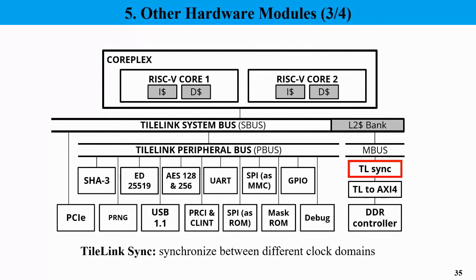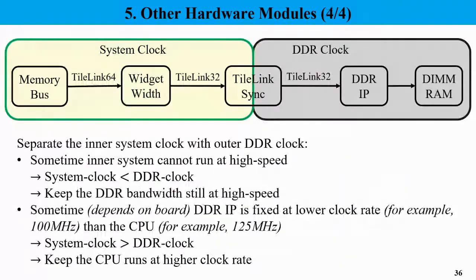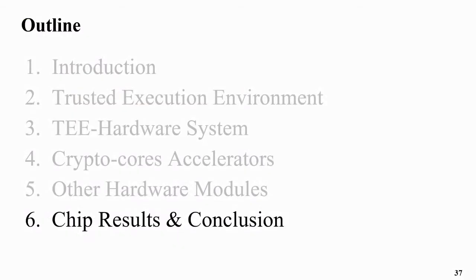The other device is the main memory controller, which is externally synchronized to match the DDR controller. In this case, we are crossing the bus and using a different clock domain for external bus control. The intention is to have flexibility at the moment of using external IP for the main memory. Usually, the memory controller handles a different clock and bus size. Particularly in our case, the IP can use a 64-bit AXI4 interface for the VC707 and a 32-bit Avalon bus for the Terasic boards. So it's different in each one of the implementations.